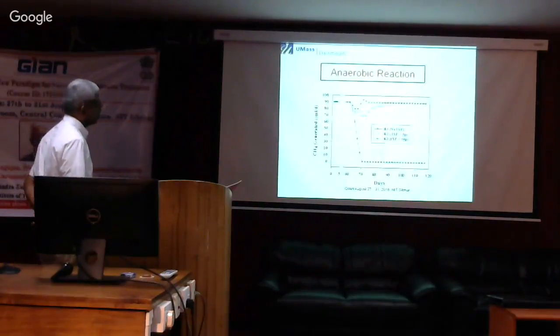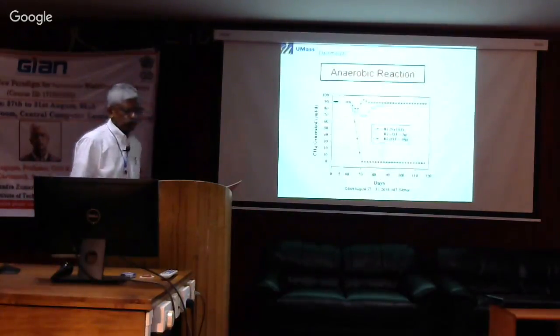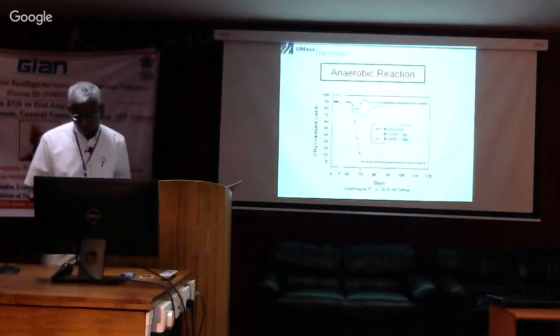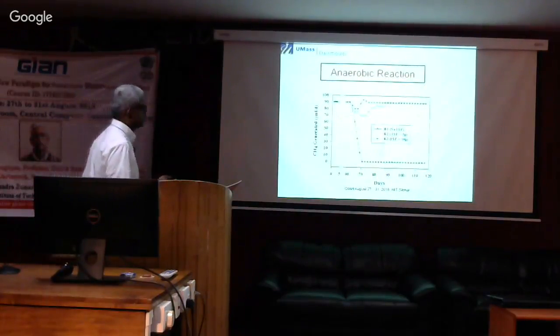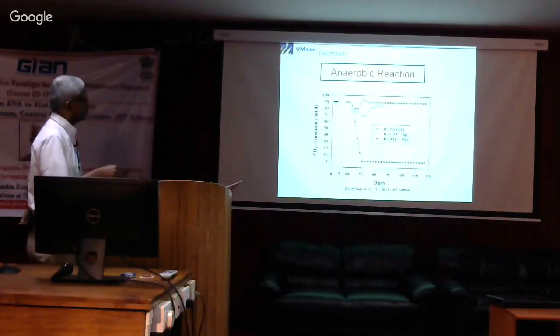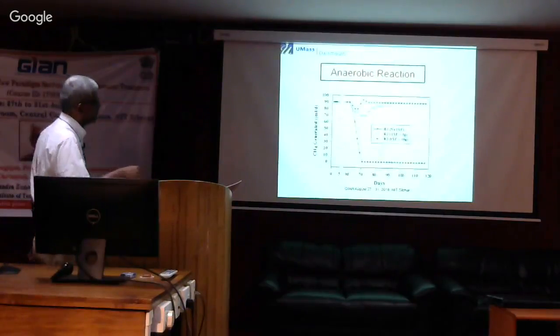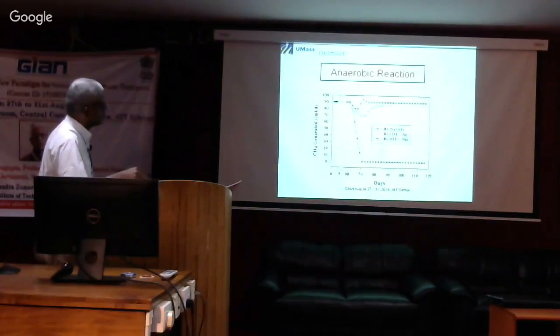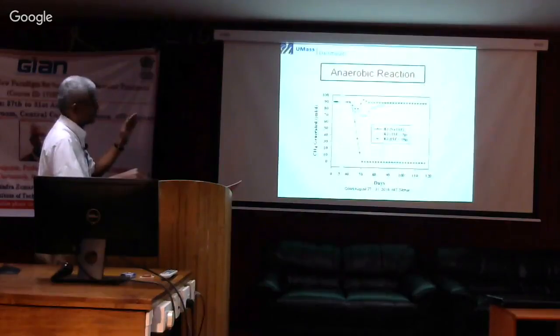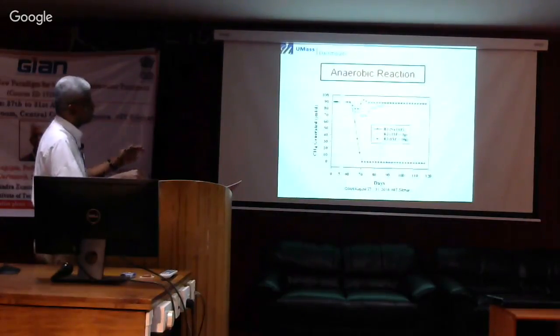Now, how about the performance of any digester? Pretty much you measure in terms of methane generation. So methane generation of reactor 1, as you can see, if the pH drops so low, the methanogens stop working, the methane generation would cease. That is what you see. Whereas reactor 2, the methane generation did drop, but after a while, again, it started to pick up. And reactor 3, it did drop, but a much lower drop, and it was able to stabilize itself much faster.